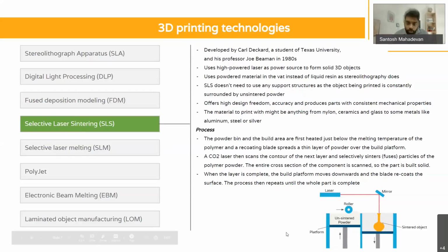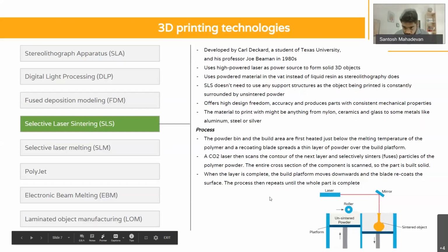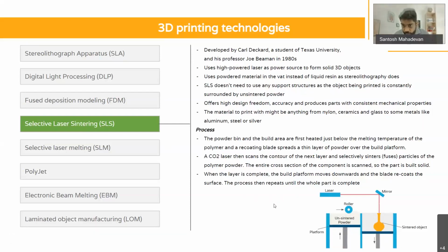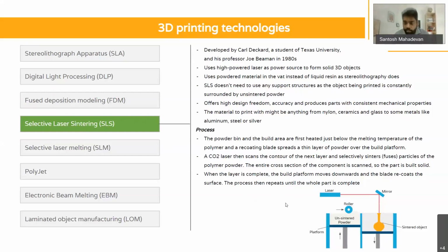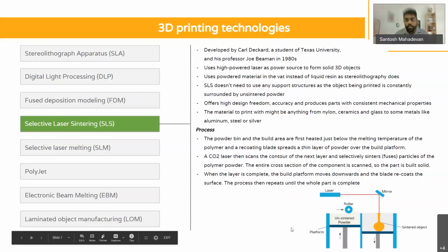But in the case of our reverse L, the moment it starts drawing the horizontal column, a portion of that horizontal column does not have the support of the previous layer. So naturally, if it is a liquid or a plastic, you can guess that it's going to be a breaking point, and the plastic might just fall off over there.